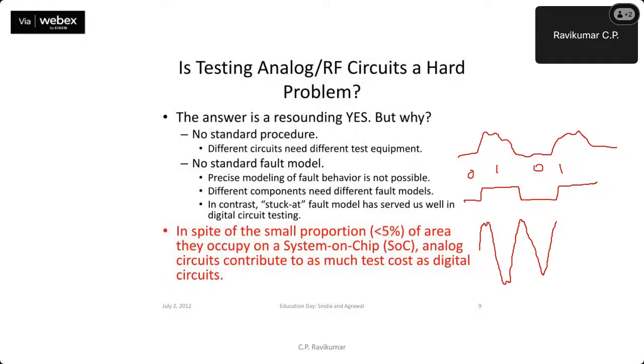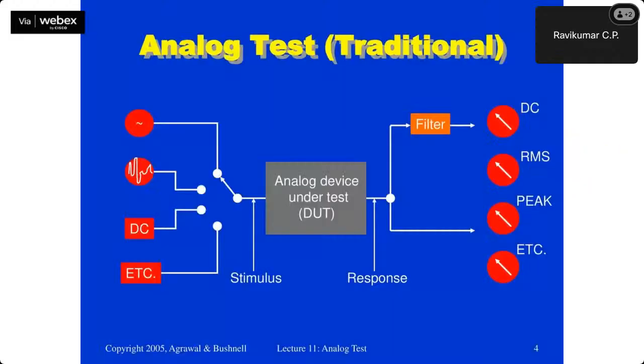So 9.9 megahertz is okay, 10.1 megahertz is okay, but anything not in this range may be rejected. We had to throw it away because it doesn't meet the data sheet specification. So that is the hard part. That is why we need all these measurements and so on.